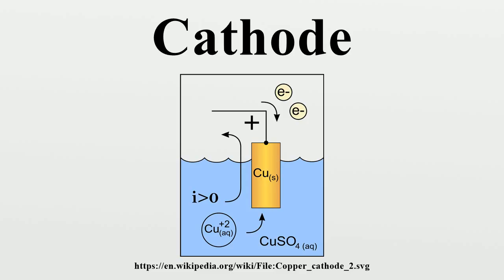In electronics, in physics or electronics, a cathode is an electrode that emits electrons into the device. This contrasts with an anode, which accepts electrons. Vacuum tubes. In a vacuum tube or electronic vacuum system, the cathode is a metal surface which emits free electrons into the evacuated space. Since the electrons are attracted to the positive nuclei of the metal atoms, they normally stay inside the metal and require energy to leave it. This is called the work function of the metal.